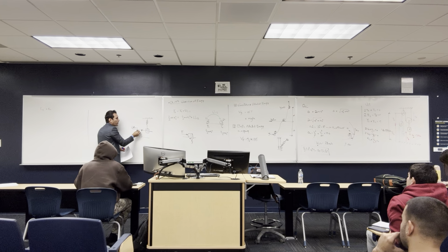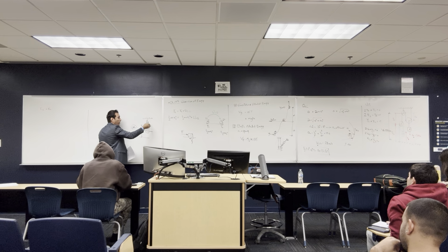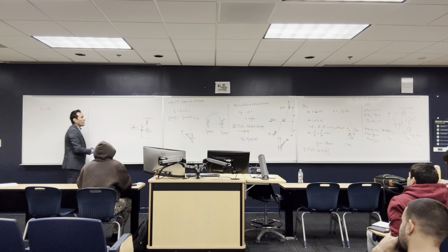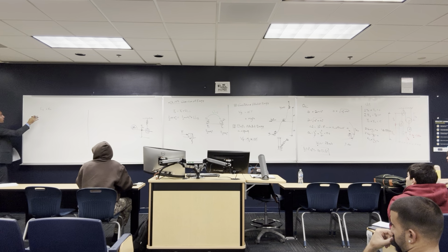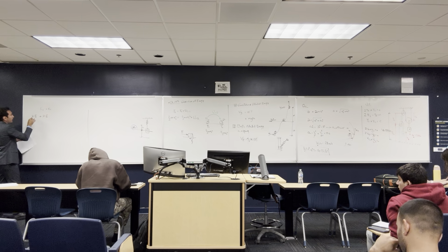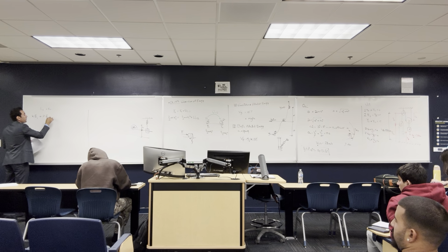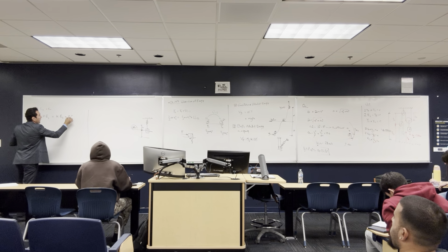All right. But once you pull it back here, it gets more energy. Or if you give it up there, the spring is going to be compressed, and above the datum you have more height, so it gives it more energy. So you're converting from different types of energy. What I want to say was that the energy at position 1 is equal to the energy at position 2, and this energy has two parts, kinetic energy and potential energy. The kinetic energy at position 1 plus the potential energy at position 1 is going to be equal to the kinetic energy at position 2 plus the potential energy at position 2.